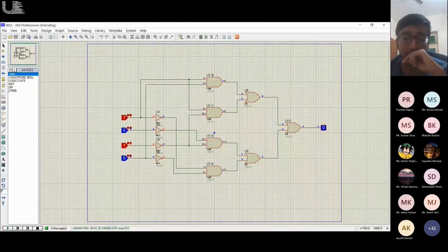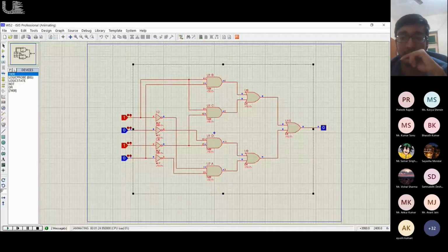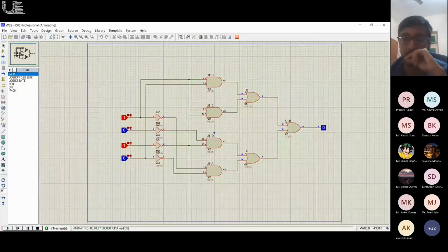Okay, so that entire function which we had right there has been simplified to just these few gates, reducing the cost of hardware by a huge extent. So that is the power that K-maps give you, right? So for 5, then even 7, 12, I should be getting a 0. 7 also I'm getting a 0, and same goes for 12. So I'm getting zeros out here. So you have made the circuit that converts the corresponding input to this output.